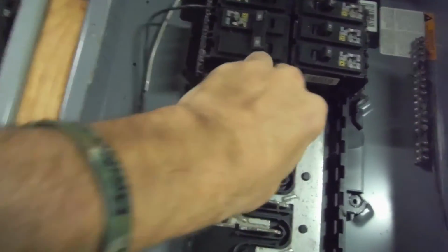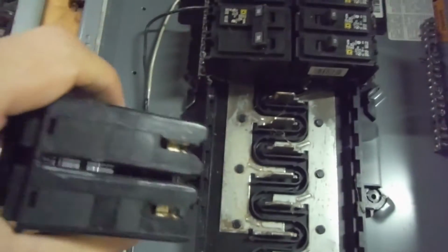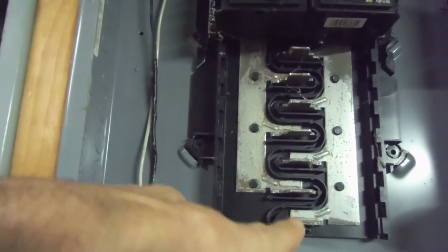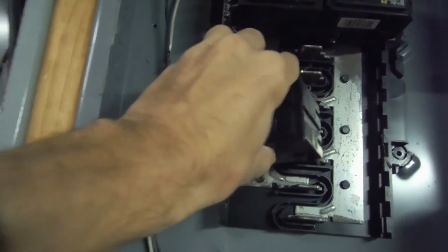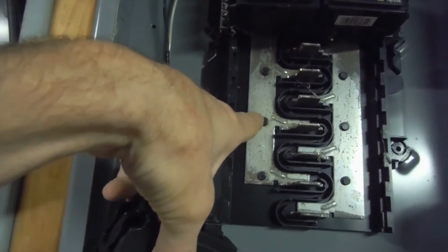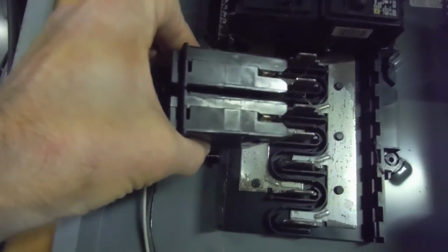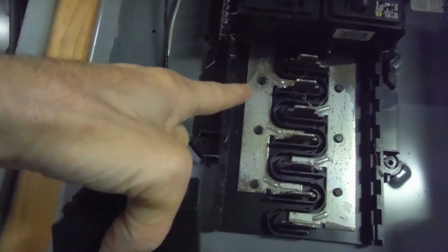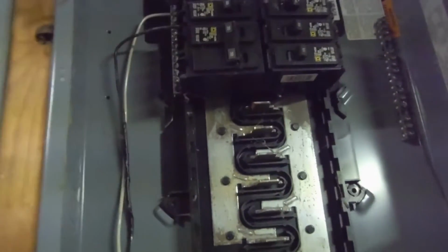You take like a 220 amp breaker, like this guy right here. We'll see how it's crisscrossed here. That's made so whenever you plug one of these breakers in, it's getting 120 from this leg and 120 from that leg. That way you get one from each, and you're not grabbing two from one. And the reason is that way you can keep everything even.